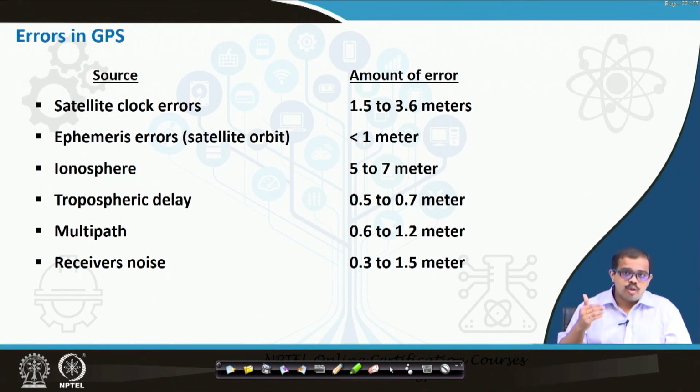Whenever you are going to the field, first look at what the error in the measurements is. Switch on the receiver, and look at a known point on the earth surface that you are close to. Once you have the known point, you know what error is induced into the system.